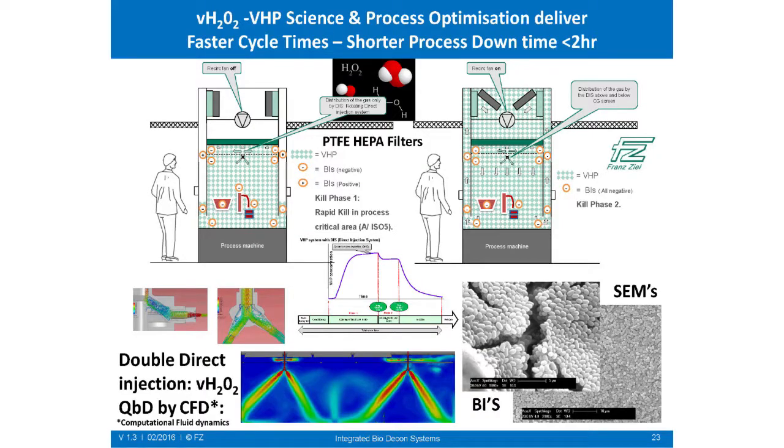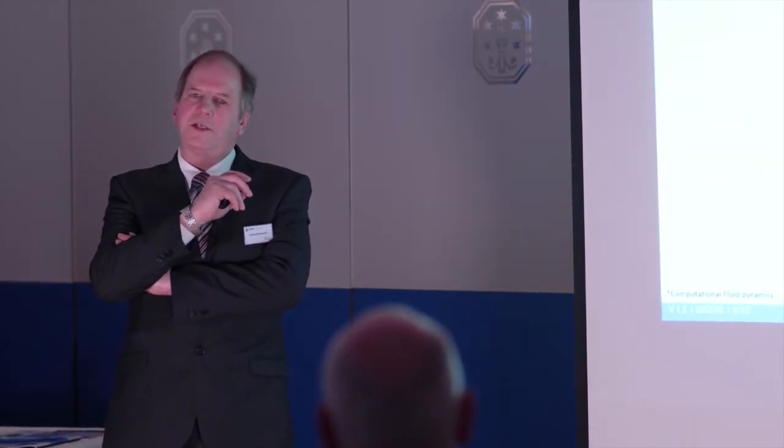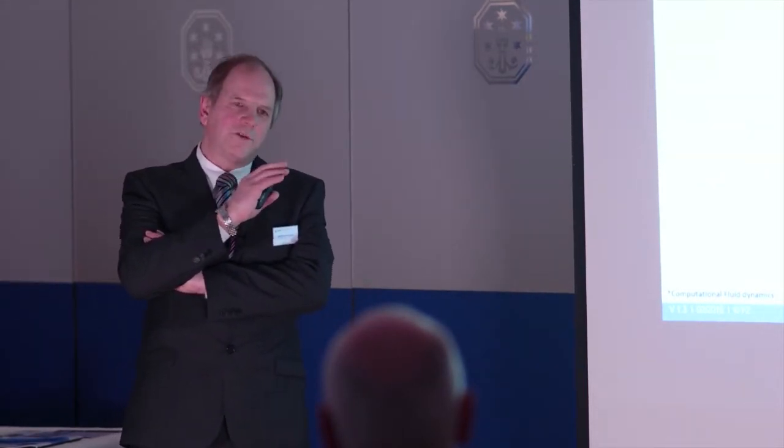Now, firstly, the most exorbitant materials in your isolator systems are the HEPA filters. So classically, we use PTFE HEPA filters these days. There's been a huge development in those, and they've been hugely effective in applying to isolator technologies. PTFE is hydrophobic and a really good starting place.